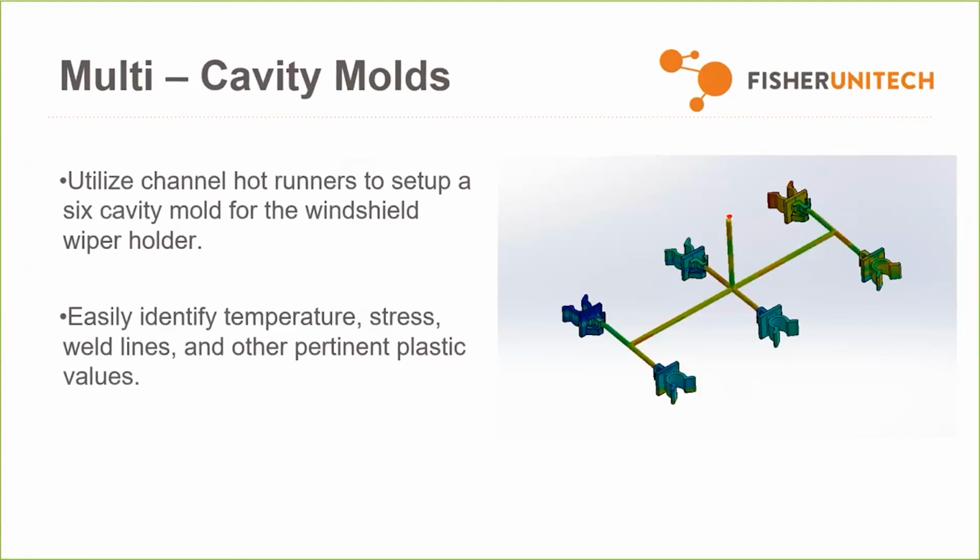So you see the runners right here. There are these pipe designs, and you can see the injection location at the top. That's the sprue coming down. It's sometimes difficult to understand how large these runners need to be. The optimum scenario is for your fill to be balanced, meaning that each of these cavities is filling up at the same time, meaning that you have a runner system set up with balanced flow.